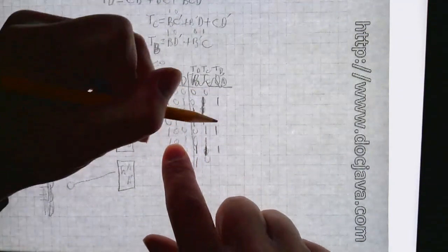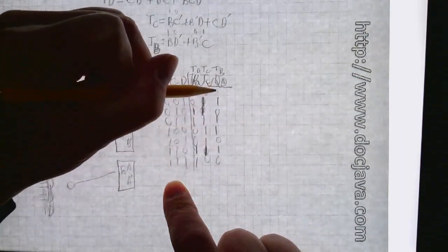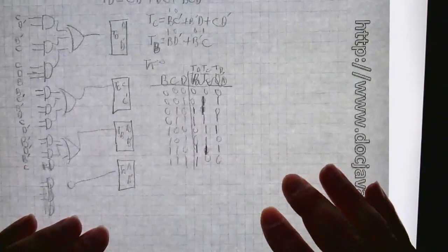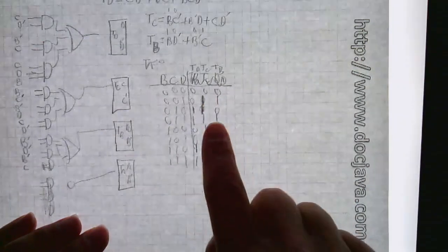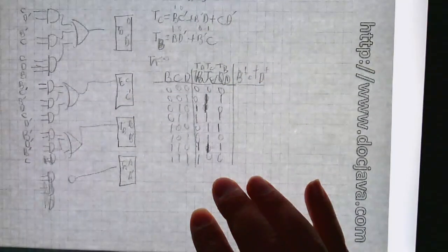And this is going to be 0, 1, B prime C. 0, 1 is here and here. The rest are 0. So rewrite this so that the columns are in the correct order, and then you'll be able to figure out what the next states are. And then you'll have a present state, next state diagram. And that's how you do that.